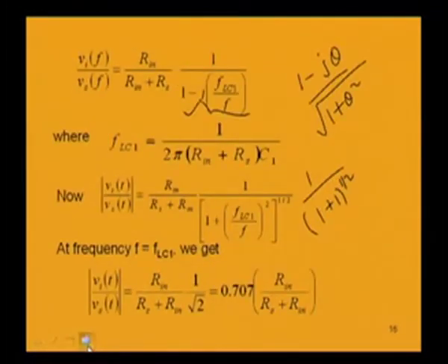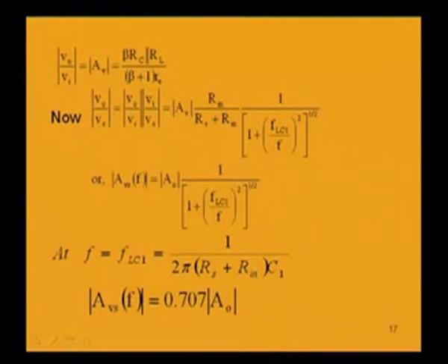That is having the relation which is known to us. So, we can replace that V naught by Vi, which is AV, that means the voltage gain, which is nothing but, if we consider the magnitude only, minus sign we are not writing, beta into RC parallel RL by beta plus 1 RE, that is the voltage gain between output terminals and input terminals. But now let us consider the overall voltage gain V naught by Vs, that can be written by a chain rule as V naught by Vi into Vi by Vs.